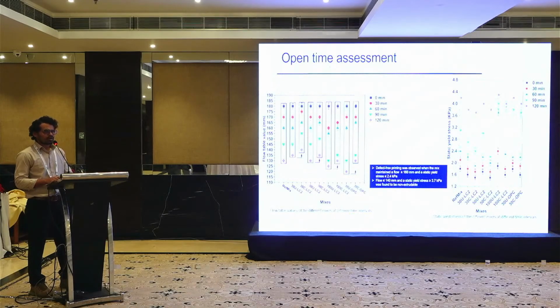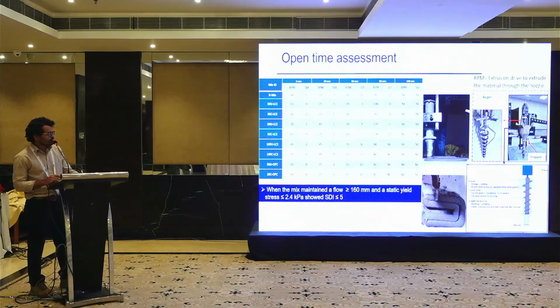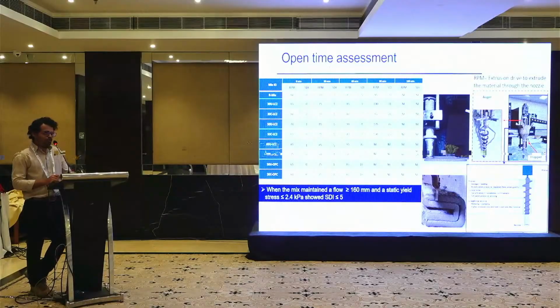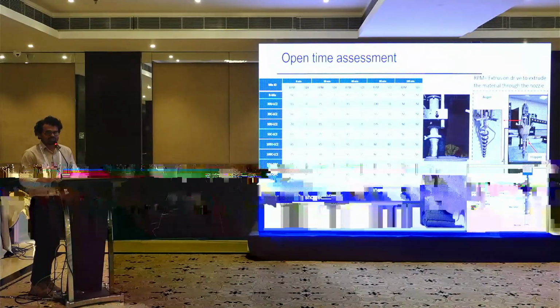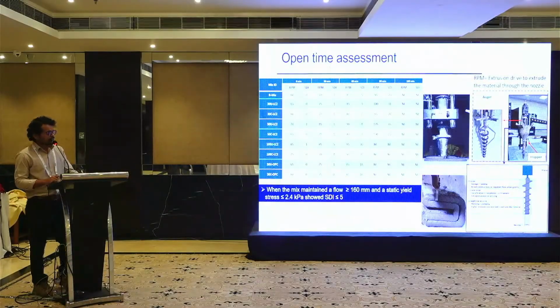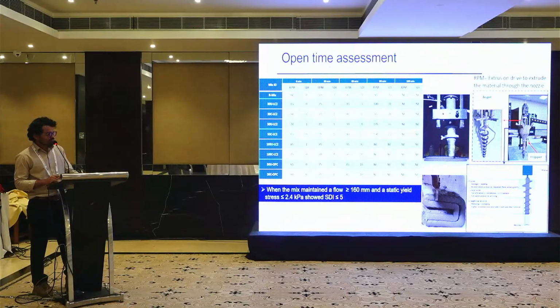And the uncarbonated mixes showed a lower flow table value compared to the carbonated mixes, and the static yield stress for the uncarbonated mixes is higher compared to the carbonated mixes in the initial stages. And again, this table shows two more parameters which I used for assessing the open time: RPM and also surface density index.